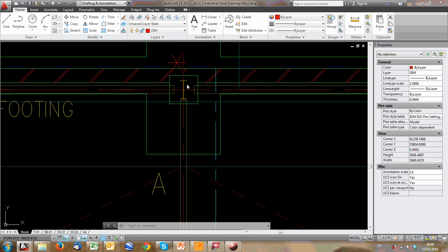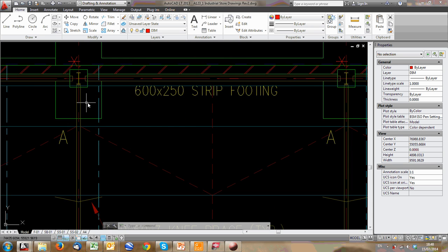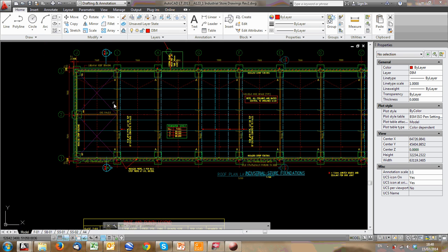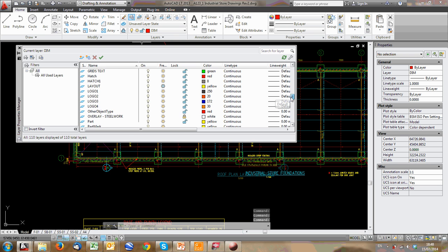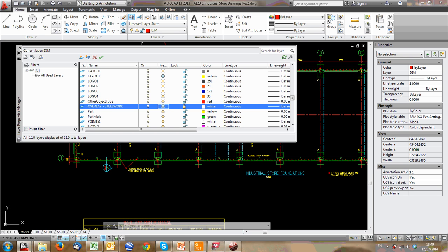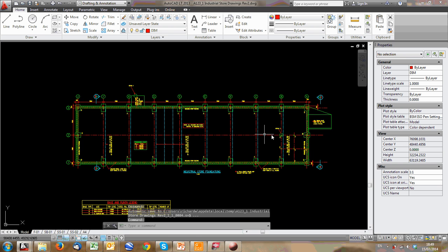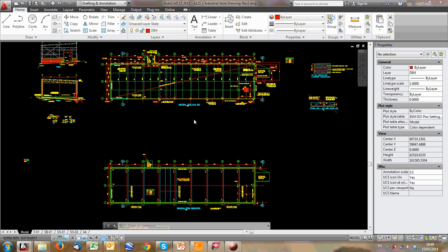Because this is quite useful, you can draw, and you can still use the snaps of the layer that's turned off. So you can go into any area and draw around it and draw on top of the layer. And then when you don't want to see it anymore, you go back to your overlay, you freeze it, and it's gone. It's still there, so if we ever want to make further changes in the future, we can unfreeze it and we can edit it again. At least that's a very useful tool for interfacing your concrete and steelwork.